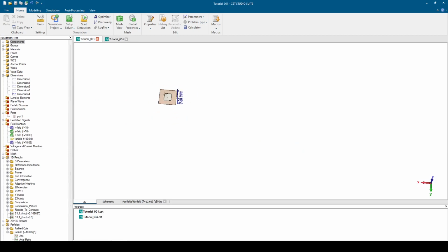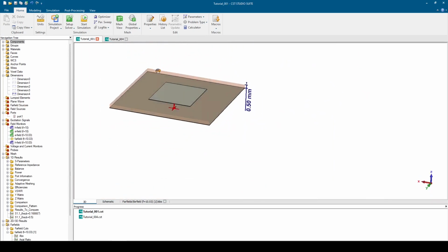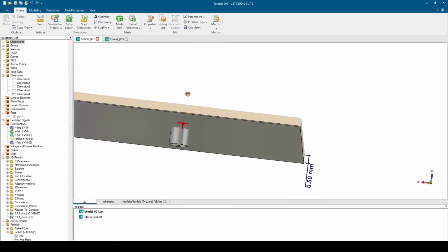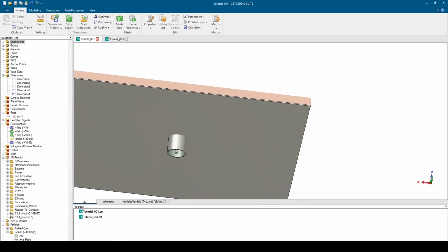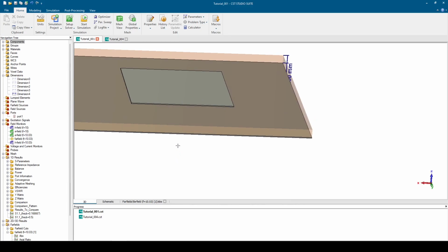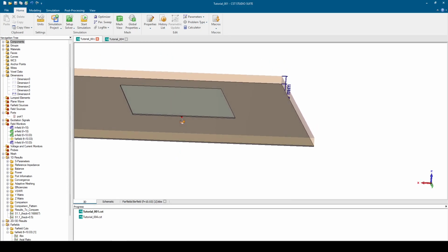For the coaxial feeding, it is somehow E-coupling, or electric. The via here feeds vertically. It is a little bit different because we couple by the E field, the electric field, so it is maximum at the edges and very weak near the center.